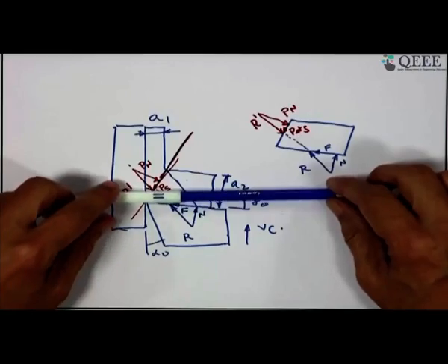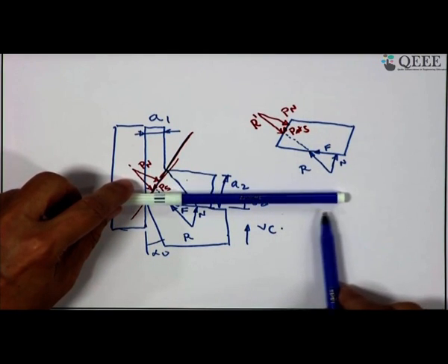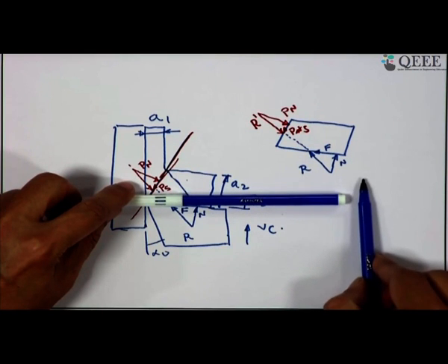However, for say design of the thrust bearing and other things, we need to know the feed force also, and the radial component of the thrust force in the y direction, that is most harmful, most damaging, because in this direction what happens, if I consider, say I would like to show you, this is a workpiece and this is the cutting tool, and the radial component will be in this direction.